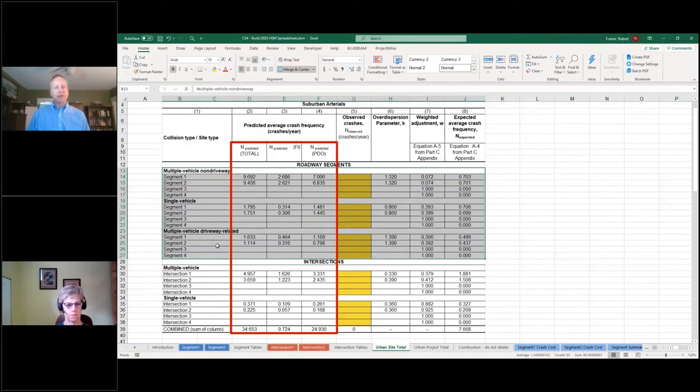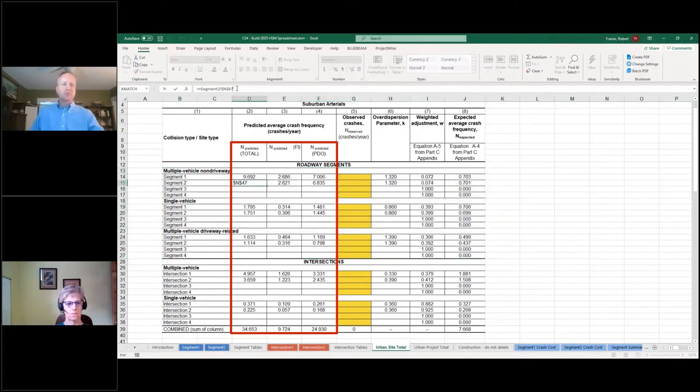So there are three sets of calculations the spreadsheet does for each roadway segment. This was a question yesterday and today: if your project fits the default spreadsheet setup, fine, but if I had a project with 5 segments, I would need to copy the tabs and reference them in. The first 2 are referenced. If you click in D14, you'll see it's a reference to another cell in the workbook. So if you add other segments, you copy the tabs and reference them in here manually.